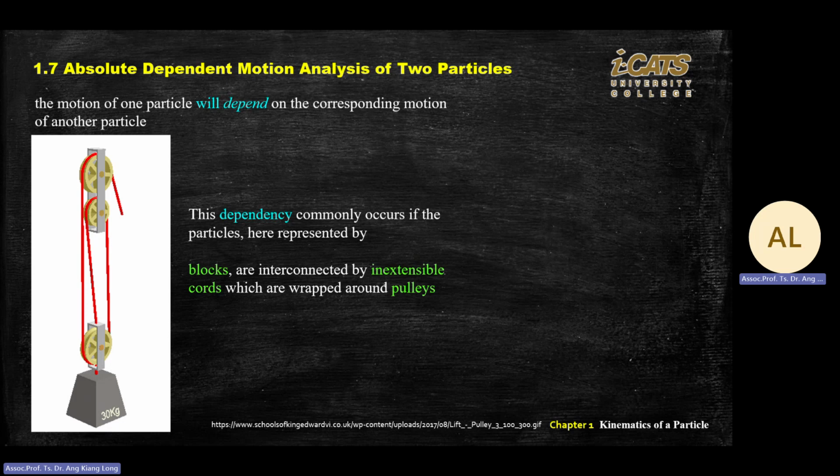you'll be given mass. So when there is a mass, then there will be W. Mass always focuses on the center of the object. So start from today onwards, in all your answers, when you see an object, I want to see you label where the center of mass is. I want to see a dot in your free body diagram. This is important. If I do not see this, it means your weight will be wrong.